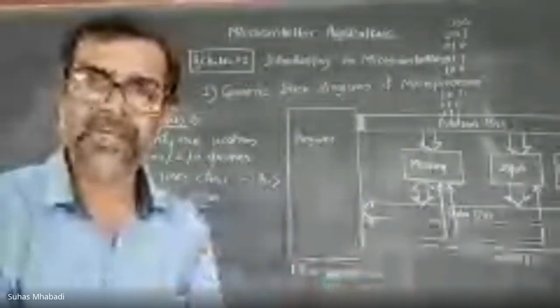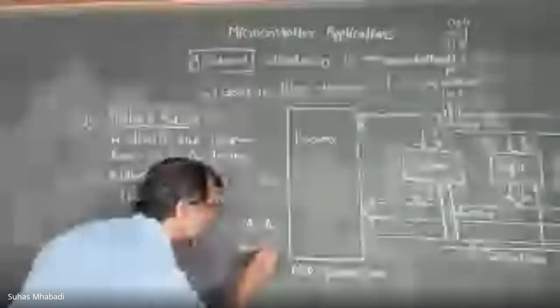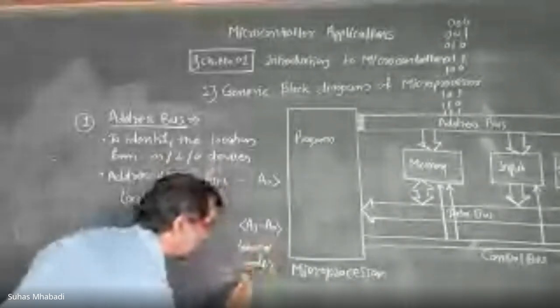Do you understand what I am saying? Yes, sir. Now what to see is how many there are. It depends on the variant: 8085, 8086 or different controllers and processors have different address bus sizes. But practically, out of this entire set of lines, the first lines A0 to A7, the first 8 lines, 0 1 2 3 4 5 6 7, are called the lower order address bus.